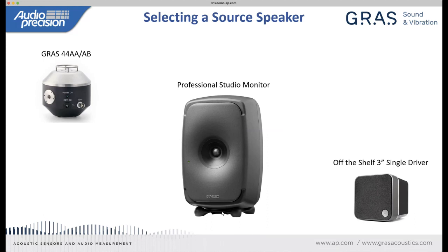If you are testing microphones, particularly for voice applications, so a microphone that's going to go into perhaps a mobile phone or a smart speaker, and you know, the bandwidth is 200 or 400 hertz to 8 or 16 kilohertz, and really the goal of the microphone is to pick up speech signals, a further property of the device may be a requirement to test it against voice telecommunication standards.